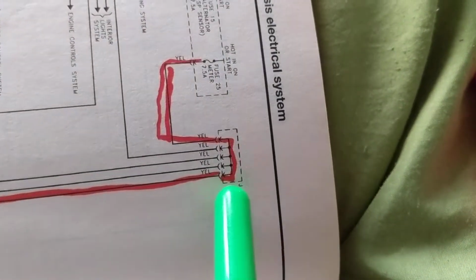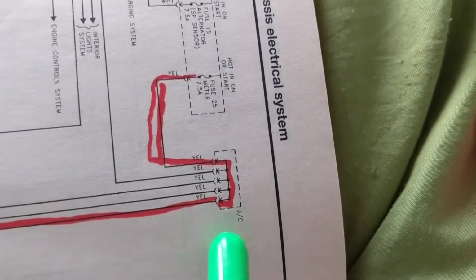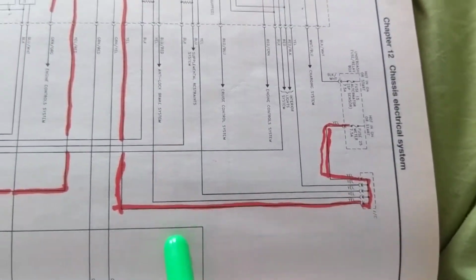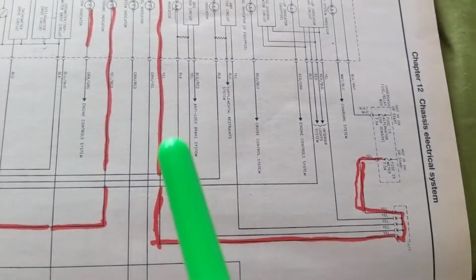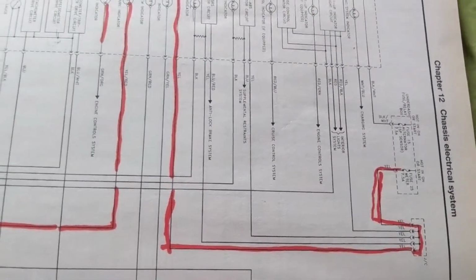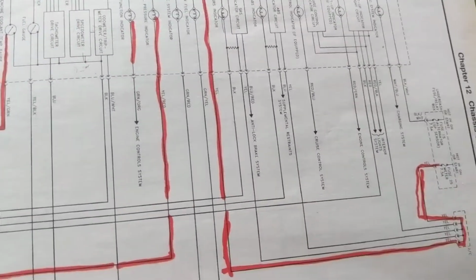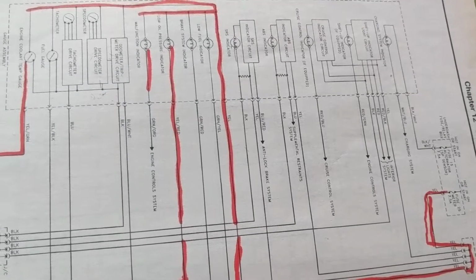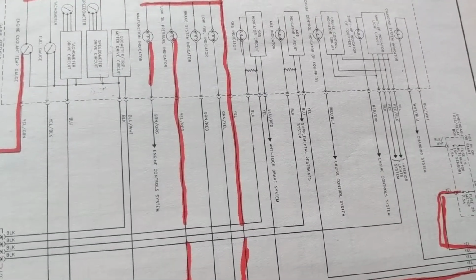What do we go through? We're going through this junction connector. And sure enough, here it is. We're going to the fuse to the 12 volts. So, what I said before for other makes and models, isn't it true that it holds for Hondas? See, it's the same concept. You don't have to make 1,000 videos for each individual make and model of everyone.